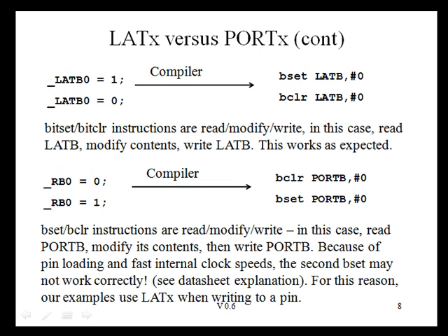So the bottom line is that when we're writing a port, we're always going to want to write to the LAT bit. We're not going to want to write to the port bit. So let's say that again. When we're writing to a port, we're going to want to write to the LAT bit here. We're not going to want to write to the port bit.